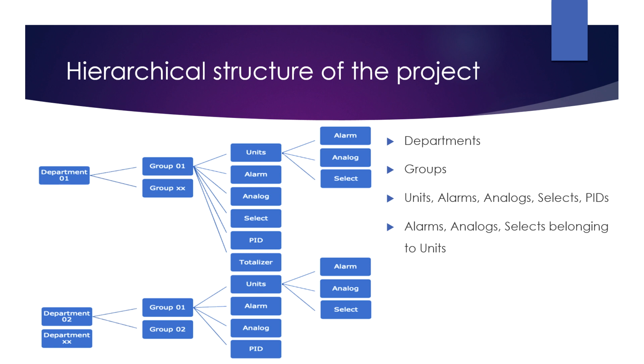Units may have additional components assigned to them, such as alarms or analog measurements. For example, in the case of a drive controlled by a frequency converter, any alarms related to converter faults, as well as status data, will be assigned directly to that drive unit. This ensures that information about the status of each device is easily accessible, and any malfunctions can be precisely localized.